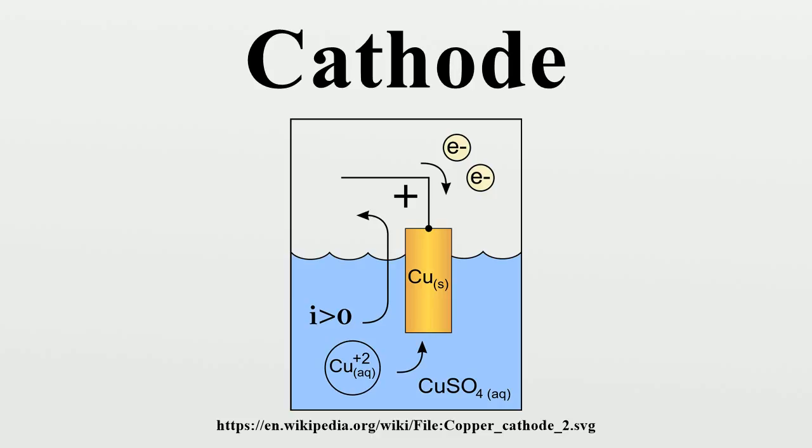Electrons which diffuse from the cathode into the p-doped layer, or anode, become what are termed minority carriers, and tend to recombine there with the majority carriers, which are holes, on a time scale characteristic of the material, which is the p-type minority carrier lifetime. Similarly, holes diffusing into the n-doped layer become minority carriers and tend to recombine with electrons.